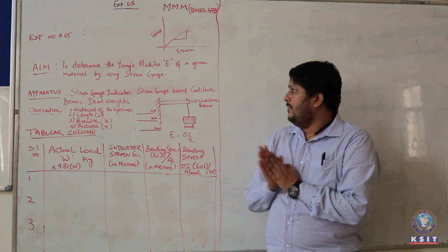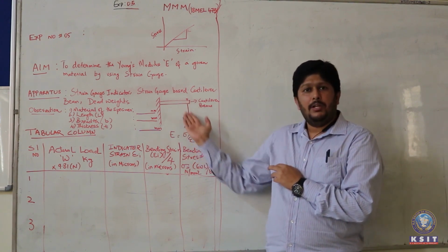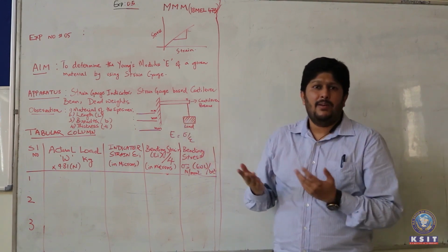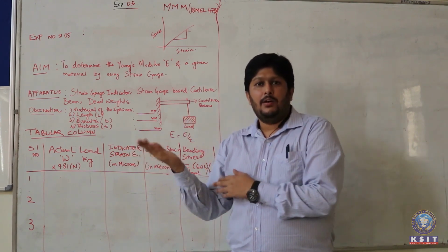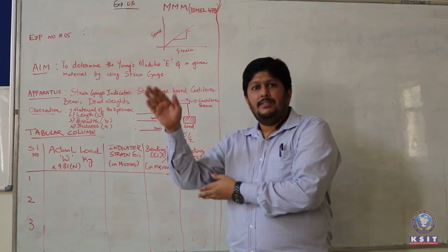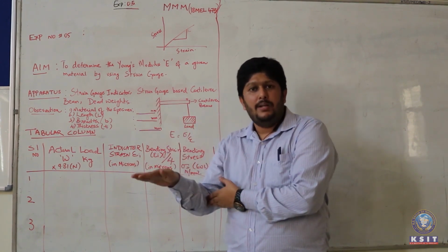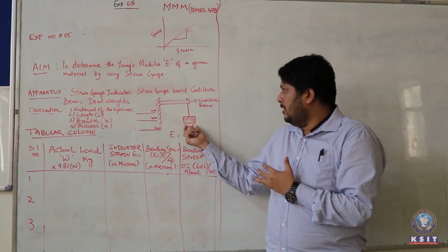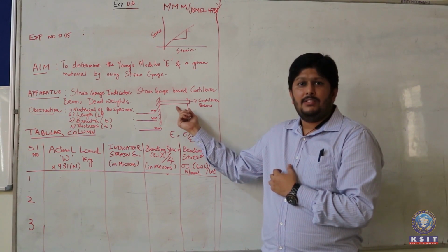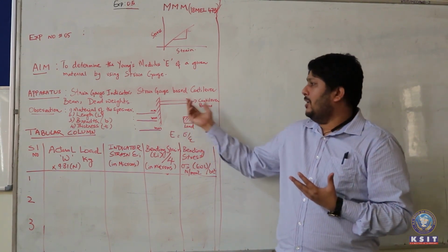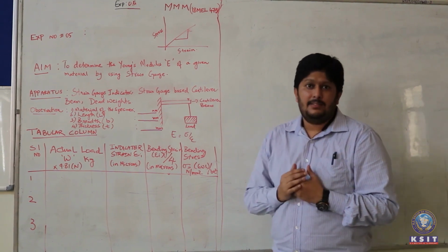Basically we have a specimen and we put a load, and when we put the load, there is a deflection in the specimen. It's very simple. Take a steel ruler, not a plastic ruler, and put some pressure on it. You can see a deflection. Deflection is nothing but movement, so we can record the movement. When we put the load here, there is deflection, that is, a change in either length or certain dimensions, and we are recording the electrical resistance.